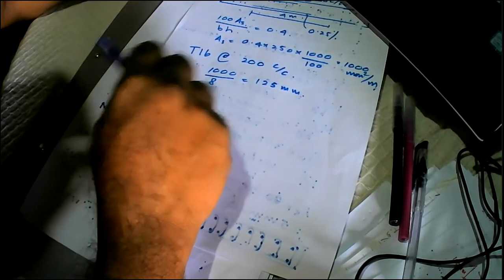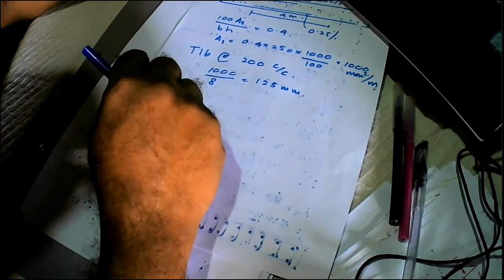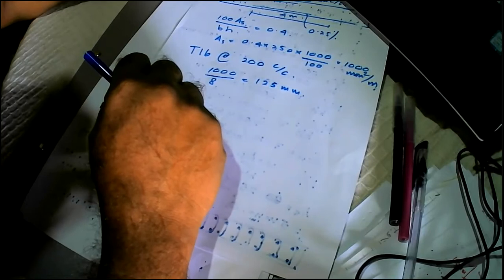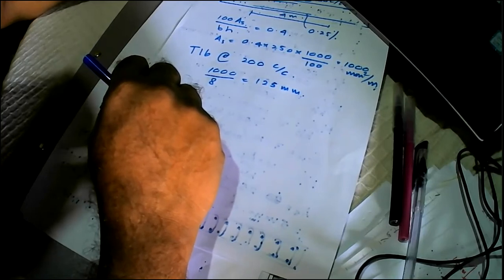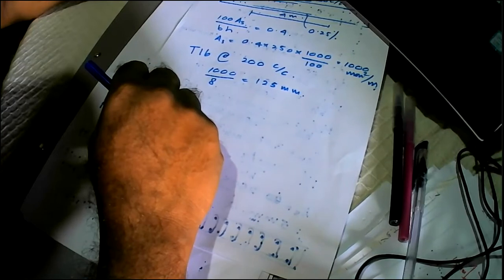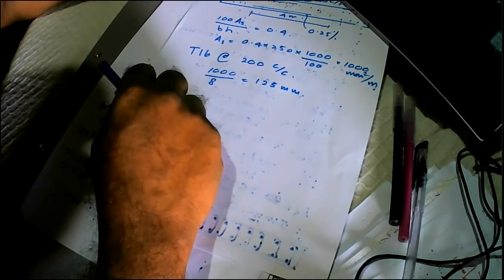But anything between 0.6 meters to 1 meter will be okay. But if you go for anything less than 0.6 meters, you will find that the distance between bars will be reduced significantly. Then you will find that, when it comes to concreting and so on, there can be difficulties. Is that clear? Yes, sir.